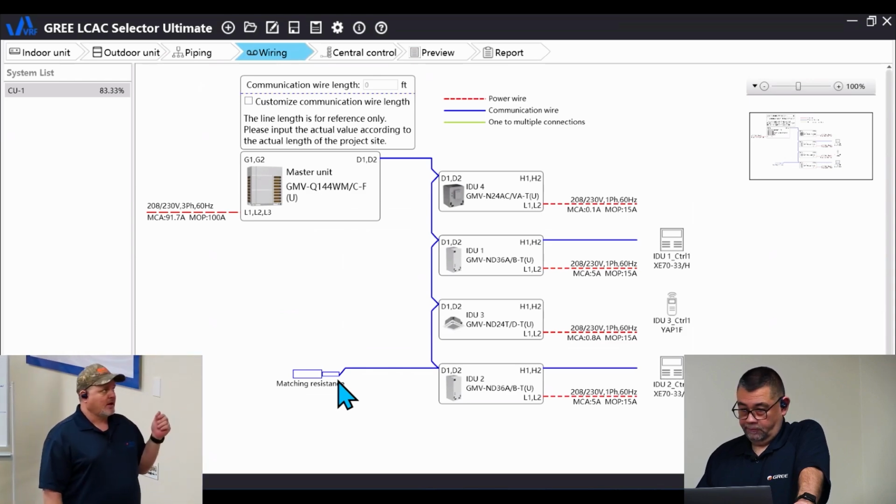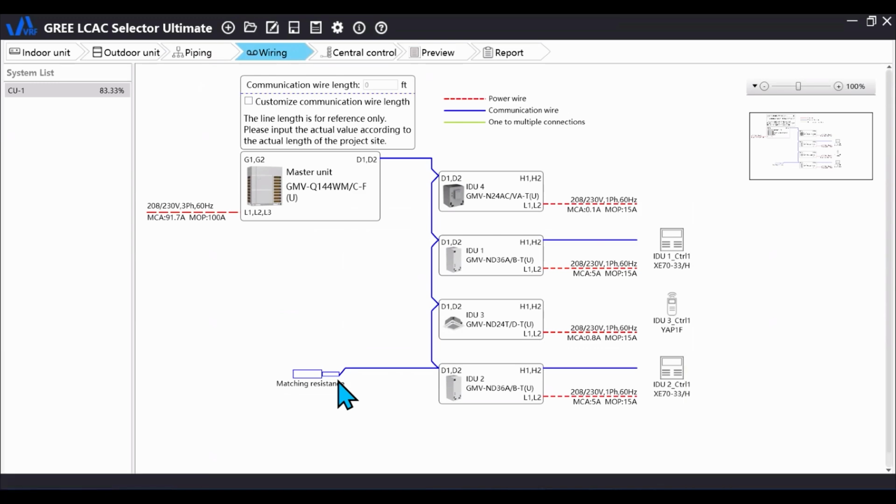That control box that's on the front of there is relocatable. I want to make sure I point that out in that picture. You see that control box. It can be moved to the left side of the cabinet. It can move to the right side of the cabinet. Your low voltage wiring will go into there. Your D1 and D2 will hook up there. Your 24 volt signals will be transferred from that board, telling that machine what to do.